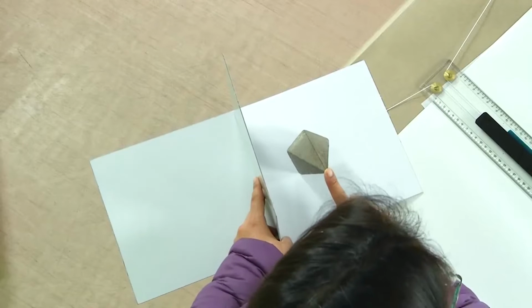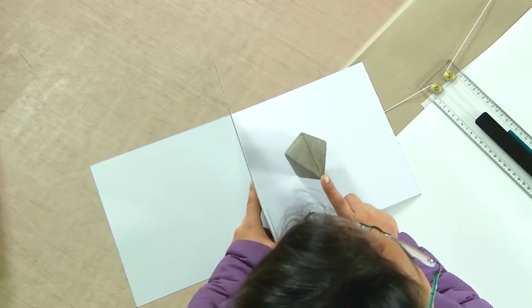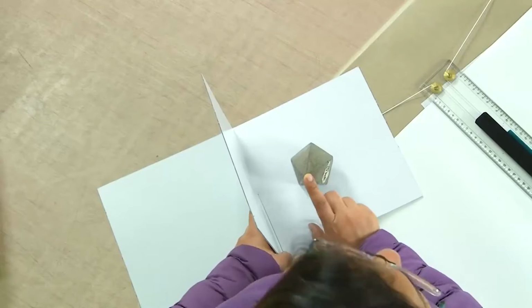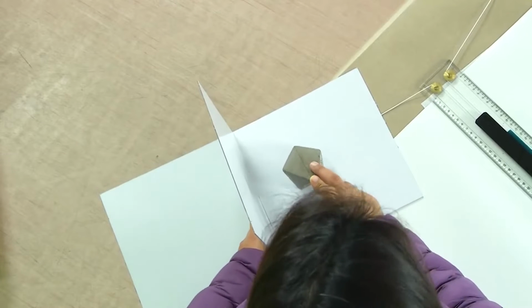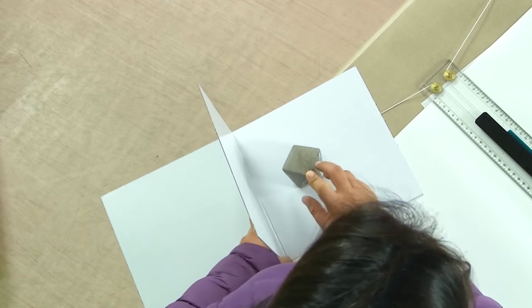Now, imagine if I incline it like this, what happens? We do not have the base parallel to any of the reference planes, but the axis remains parallel to VP. So what will we have? We will still see the true dimension of the axis, the true height of the solid, in VP, because the axis is parallel to VP, and everything else is skewed when we see it in HP, in plan.